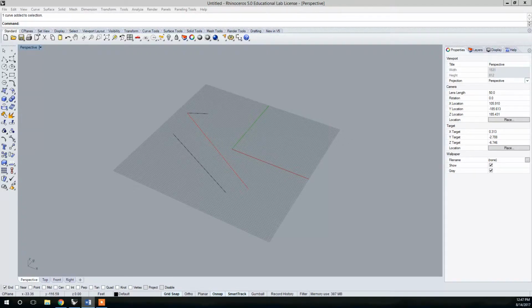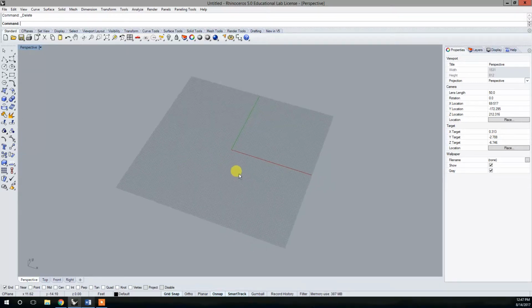All right. So I went over a lot of these interface ones, so we can move on to just the 2D drafting tools. I'll highlight all of those and then hit delete to clear my modeling space. So basically, there's the point. You can create points. I'm right-clicking to tell the command line to repeat that same command again. So I can draw lots of different points if I wanted those as center points or anchor points of some geometry that I'm going to draw next.